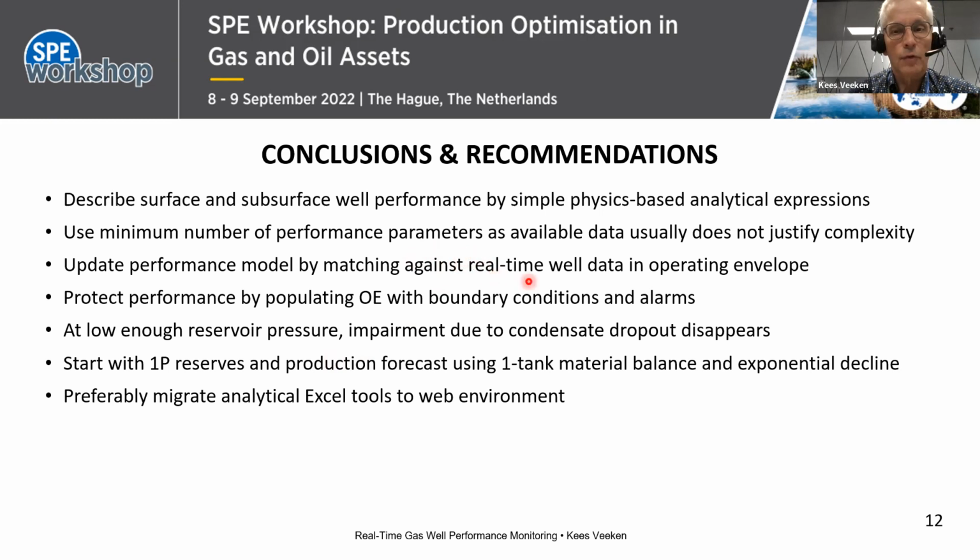Okay, and in gas wells you have all that real-time data. So you can use that very actively and very meaningfully to match your well performance curves against. And you can use the same relationships in an operating envelope that you can equip with alarms against the most common mishaps.